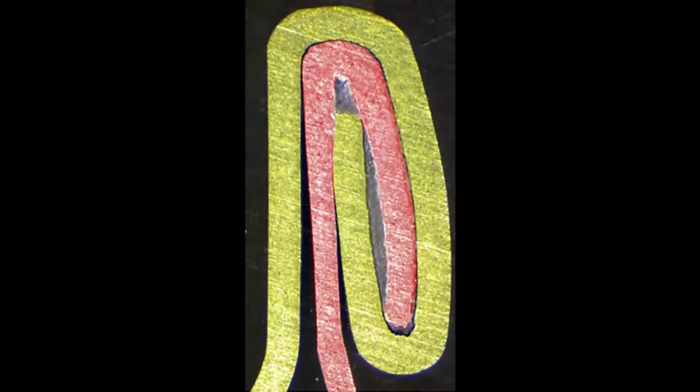In addition to the clamping of the end and can body, a sealing compound ensures that no gas escapes through the double seam. The compound is applied as a liquid, then hardens to form a gasket. The end, attached immediately after the can is filled, traps gases inside the can to create pressures of about 30 psi or 2 times atmospheric pressure. In soda, carbon dioxide produces the pressure. In non-carbonated drinks like juices, nitrogen is added.